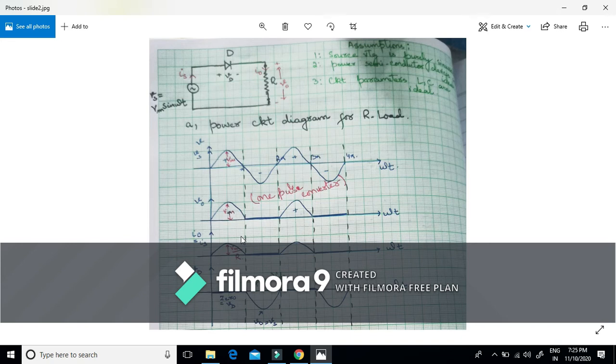Normally, during positive current accumulation of flux occurs, and during negative current that flux is given back. Since we don't have any negative cycle, no giving back of flux occurs, which results in saturation of the transformer core. Therefore, there will be more iron losses, there will be transformer heating, and this may reduce the transformer efficiency.